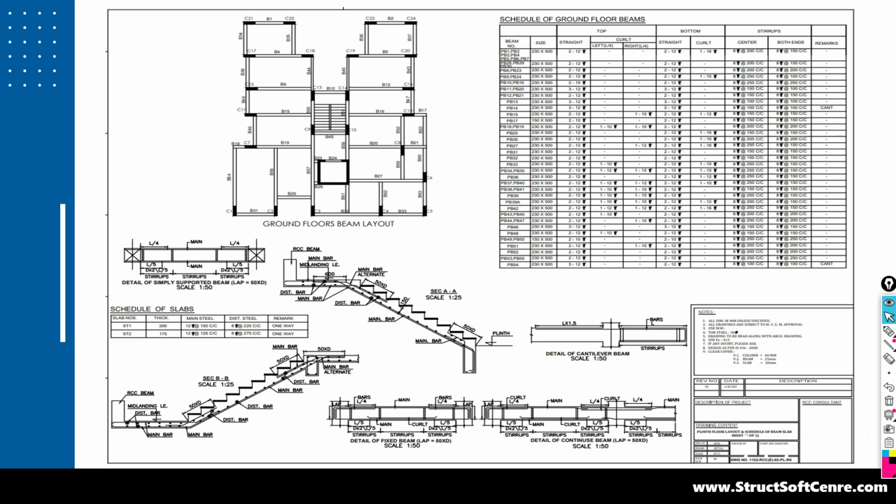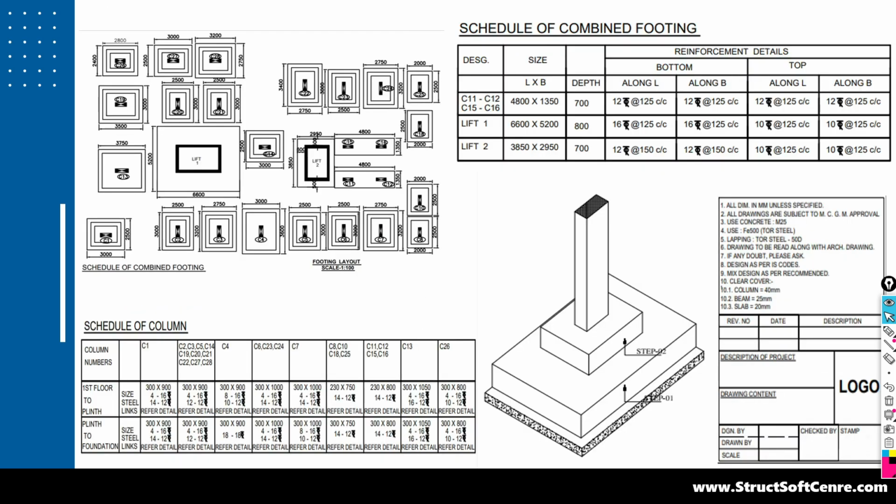For the beam, for the column, for the slab, for the shear wall, for the staircase, for every element there is a detailed discussion: what material property, what diameters of the bars, the positioning, curtailment, development length, cranking of the bars, everything is there. We are going to study the codal recommendation, then execute it here. And after all of these studies, we are going to finally prepare the schedule.